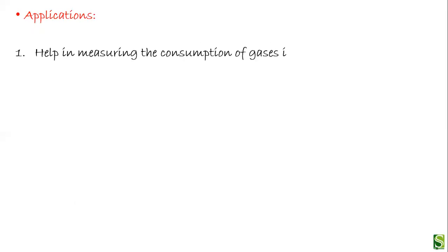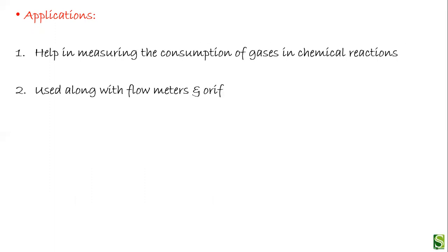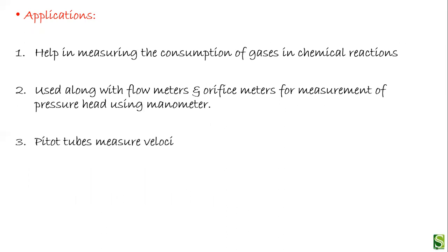Now what are the applications of the simple manometer? It helps in measuring the consumption of gases in chemical reactions. It is used along with flow meters and orifice meters for measurement of the pressure head. Also, it is used in pitot tubes to measure the velocity head.